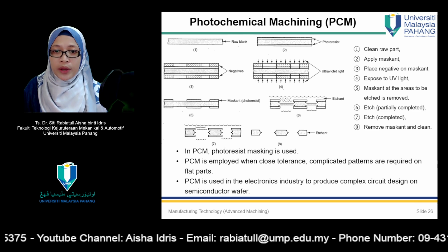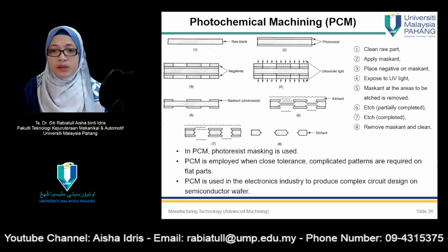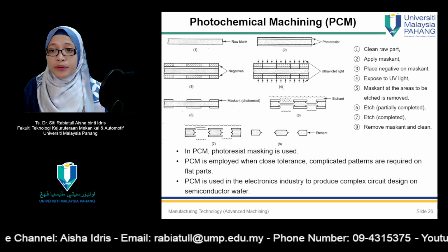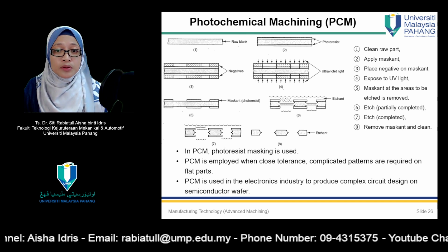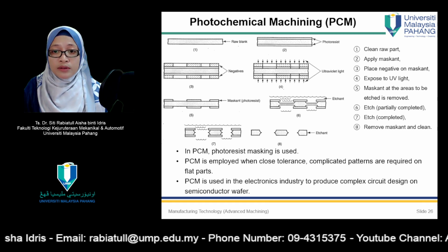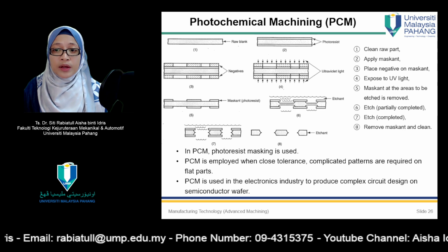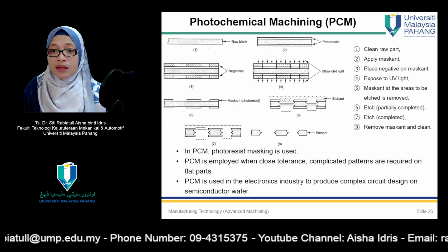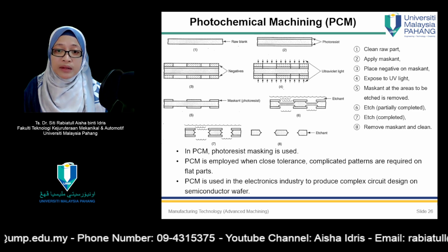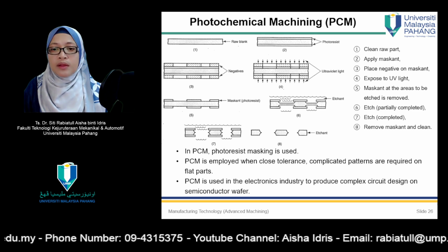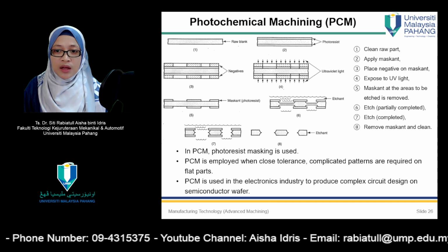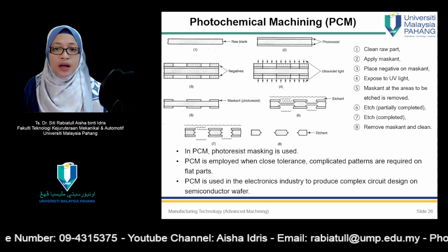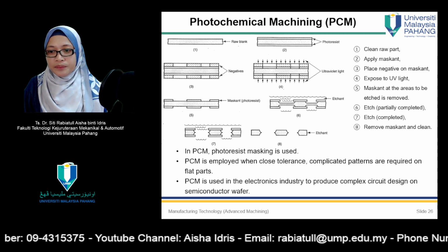There are various ways to photographically expose the desired image onto the resist. The figure shows the negative in contact with the surface of the resist during exposure. This is contact printing, but other photographic printing methods are also available that expose the negative through a lens system to enlarge or to reduce.